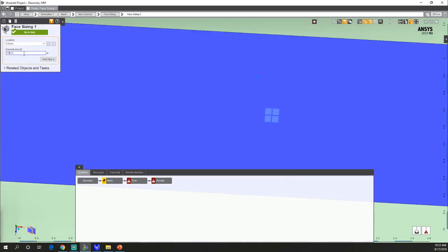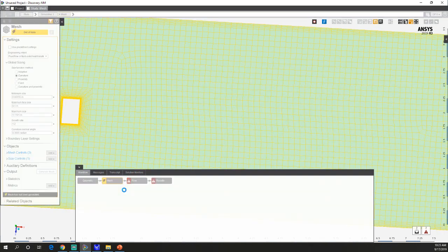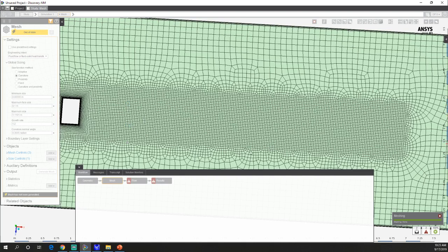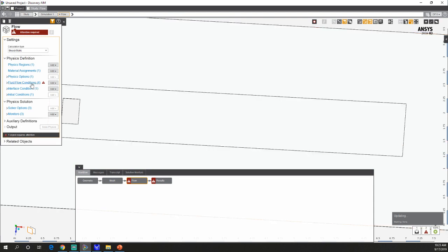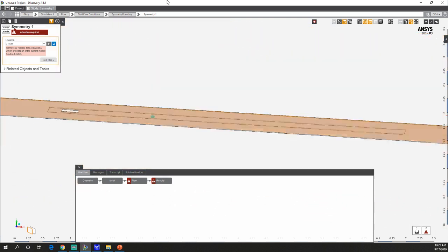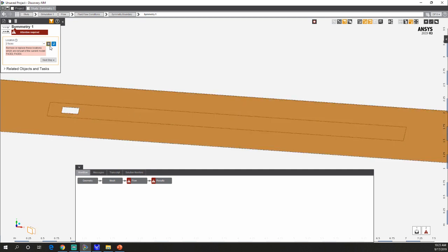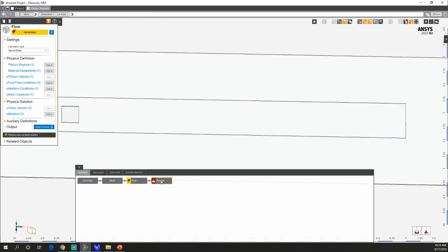We're always balancing how long it's going to take to run the simulation versus how much accuracy we're going to get out of it. So that looks like a good trade-off between accuracy and speed. And obviously, to do this formally, you want to refine the mesh and see if the values change for the variables you care about. Symmetry, because we added two surfaces, and this is saying, hey, what about these two surfaces? We got new surfaces that maybe shouldn't be there, so let's swap it out, and now it's good.